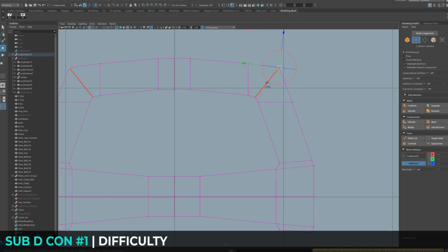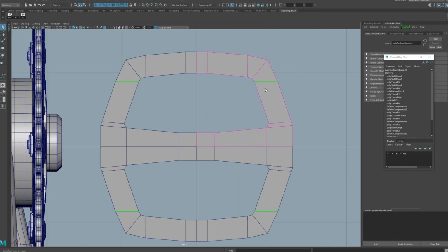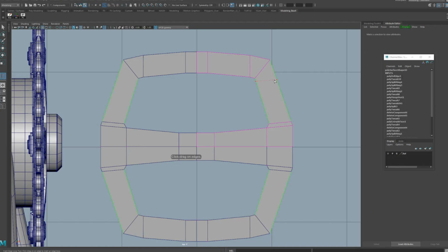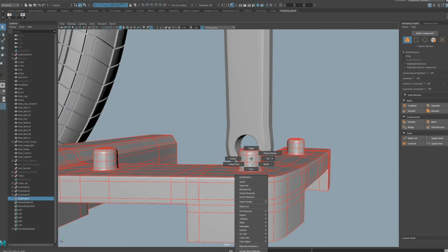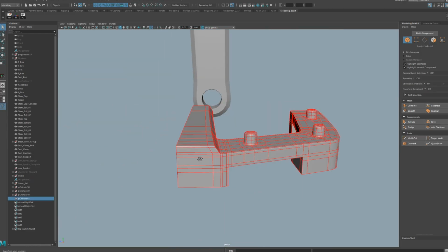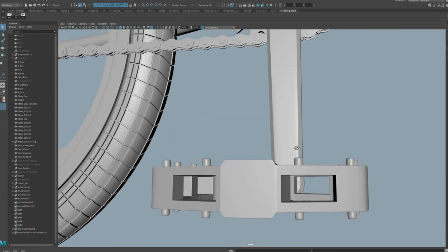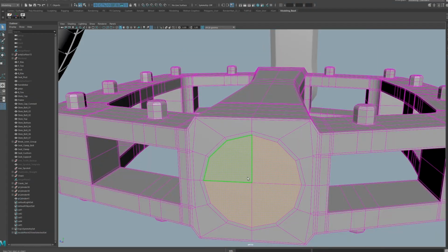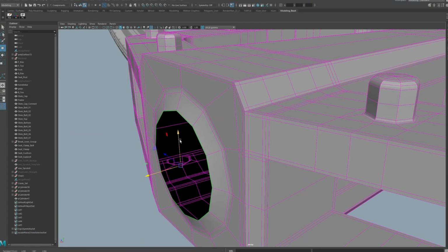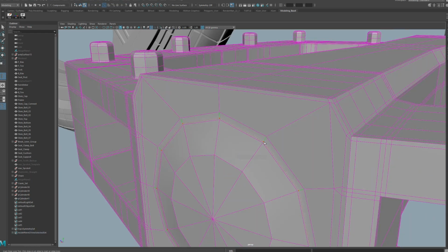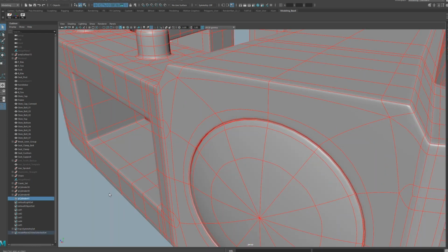Cons: difficulty. You need a high level of 3D modeling skills to create 3D models with surfaces that properly subdivide. This includes developing a good understanding of how to produce quad topology, even component spacing, and correctly adding holding edges. Curved areas can be especially tricky to keep smooth and without pinching within sub-D mode if not properly 3D modeled, while flat areas are much more forgiving.